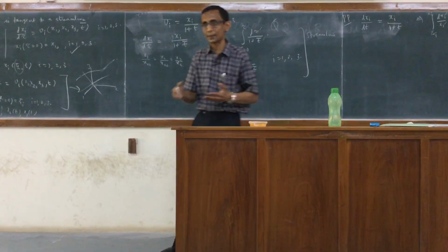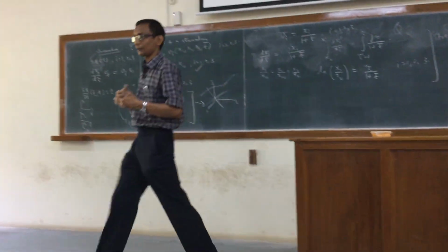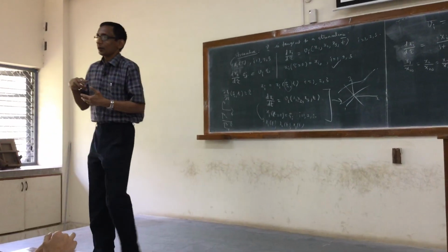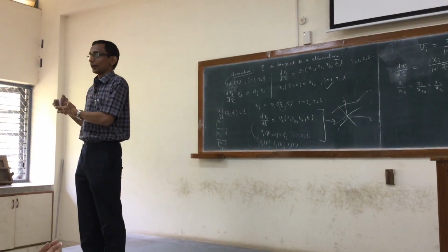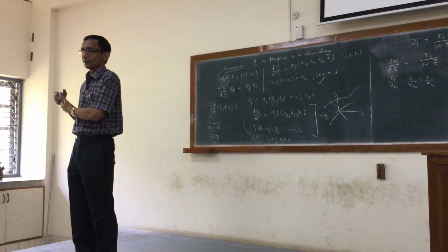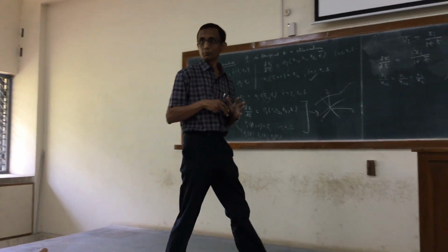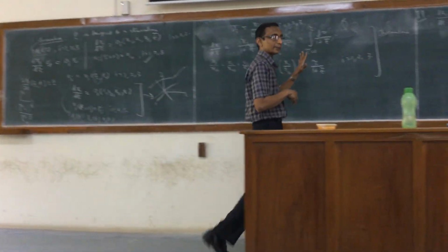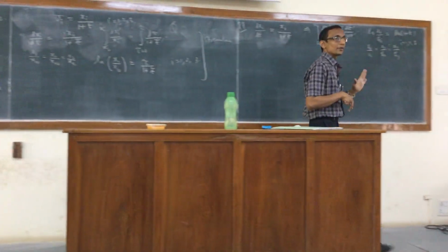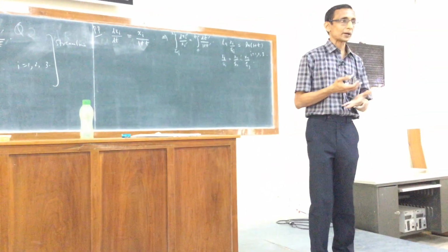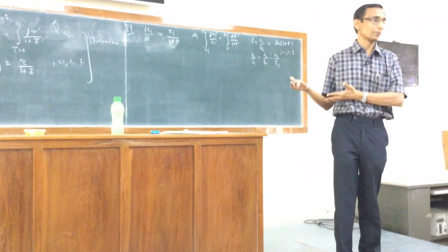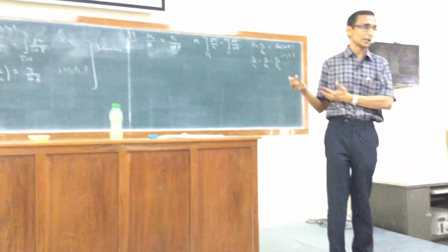So here is an example. For steady flow the two would be identical, but for unsteady flow in general they are not expected to be the same. However, in this special case, they are effectively identical. So the particle paths come out the same as that of the streamlines.